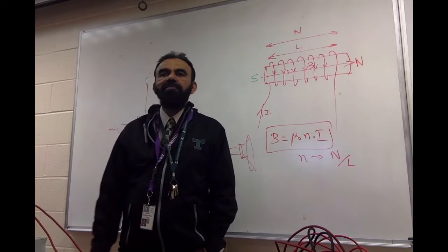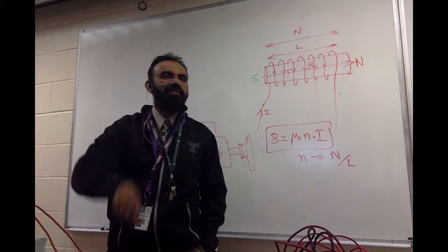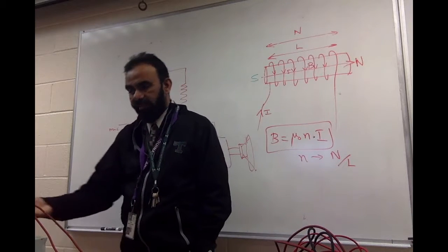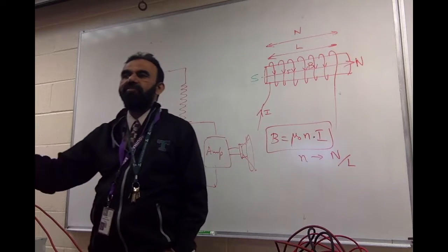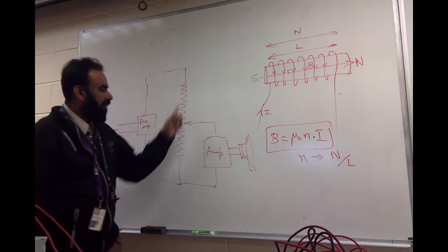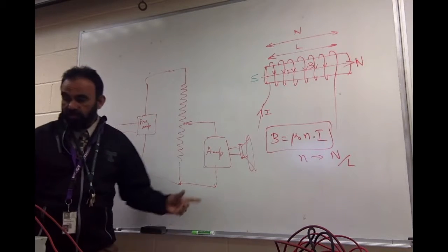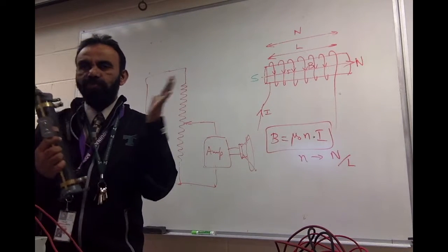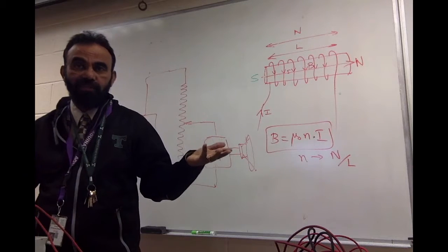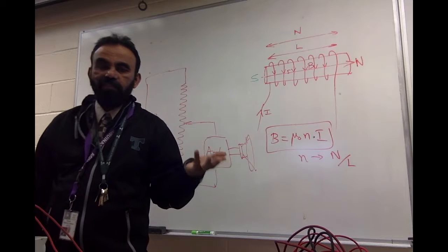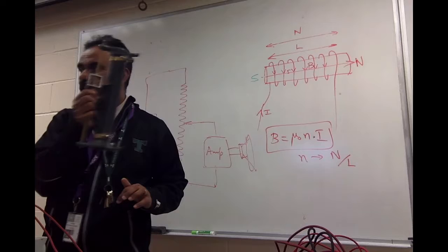Some examples? Volume control, yeah. The volume control knob itself is a potentiometer. Well, can it act as a rheostat? Can it act as this one? Well, it is not designed for that. Normally a potentiometer will have a very high resistance, like in kilo ohms. The rheostat normally will have ohms, because here your job is to control the current, not completely block the current off, right? Now the potentiometers are not always going to be made up of these wires.